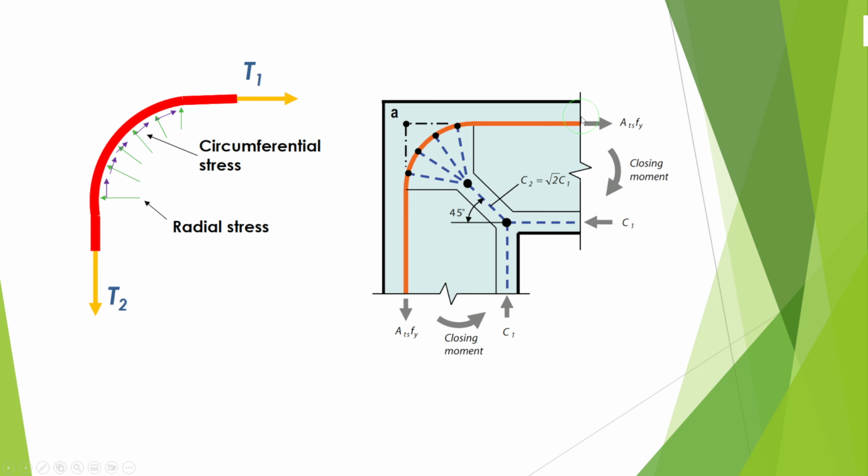If the beam depth is equal to the column depth, this will be straightforward, and as we can see here, the force will be transferred as a compression strut, with no shear forces theoretically. And here we have to satisfy a certain diameter at this curve to make this area safe, and the load will be transferred safely through this node.